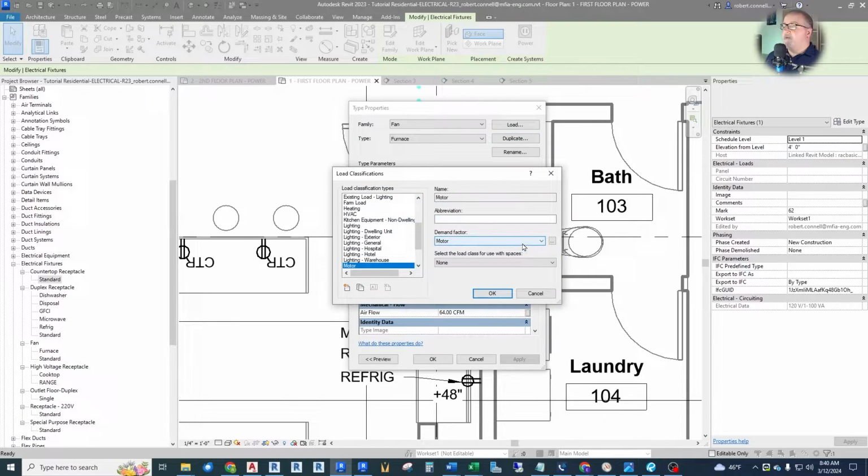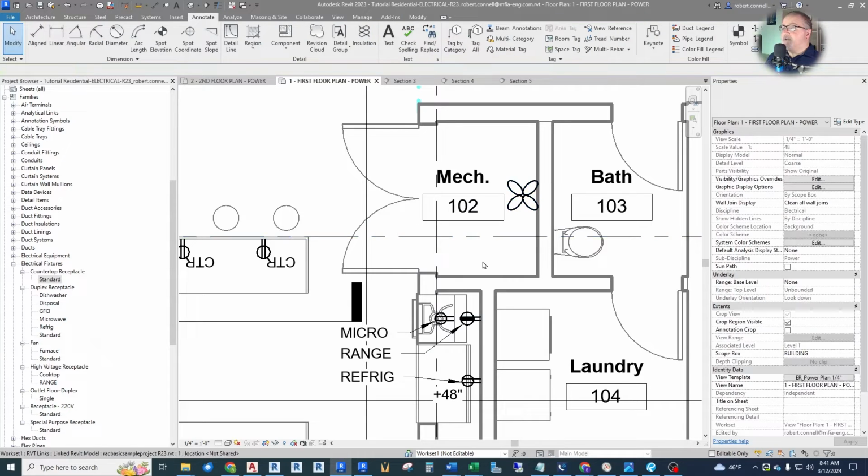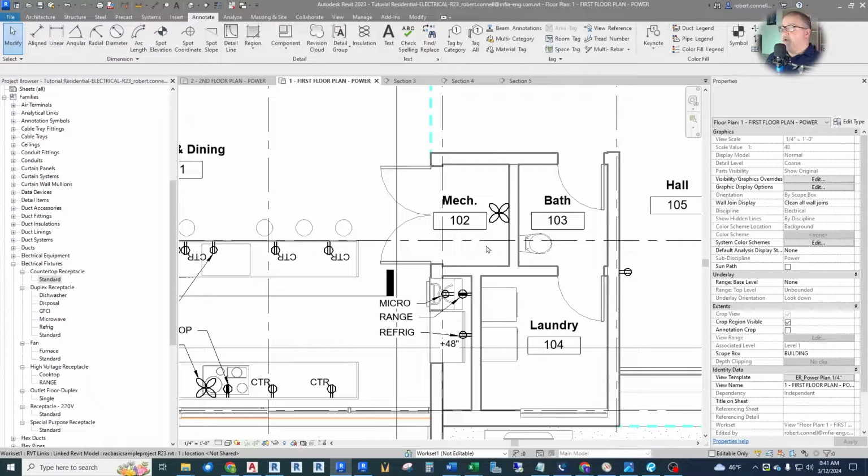And we're going to call that one actually HVAC, just so it schedules separate. And this guy is going to be a full 1500 watts on a full 20 amp circuit, not a 15 amp circuit. That's the other thing we'll deal with, is residentially, you'll see a lot of 15 amp circuits. So we'll go 20 amp there.